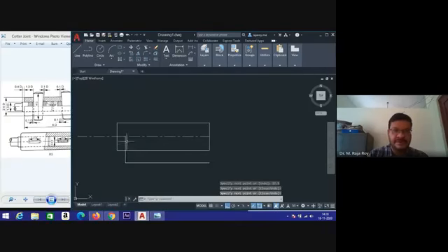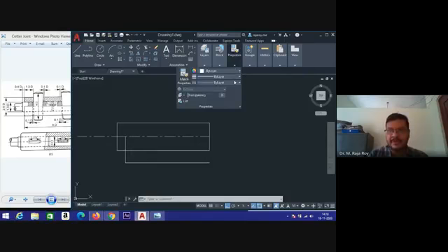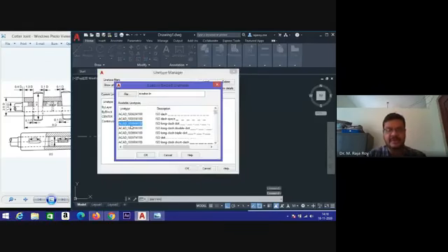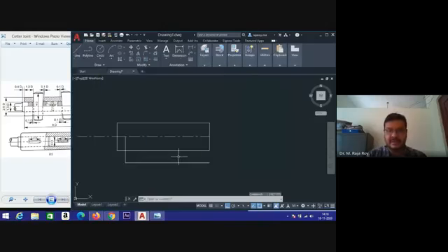Now you are getting this particular part. This part you have drawn now. Here this part is only the solid line. The remaining part is dashed line. So the dashed line type also you have to load. Go to properties, go to line types, then click on load. Here you select dashed line. So this small portion you have to get as a different line.